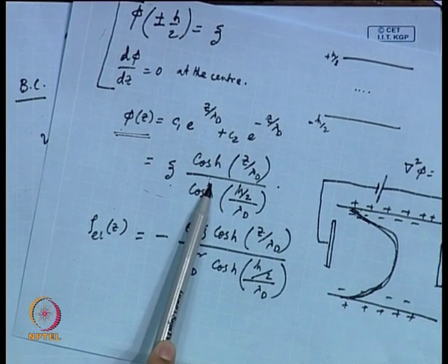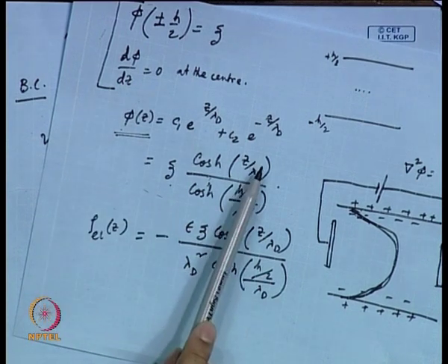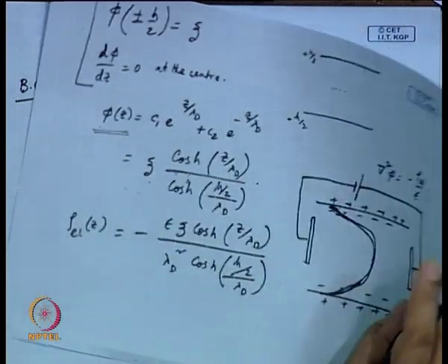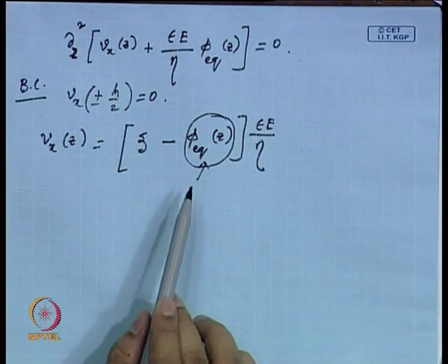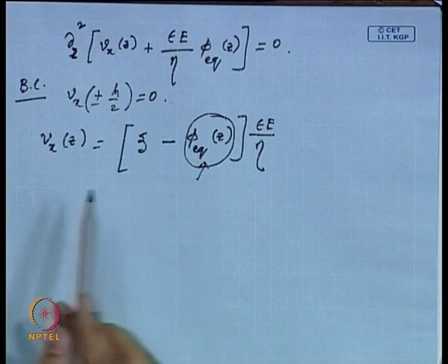All right. So, this phi we intentionally developed for a channel with two walls, to be used as part of this expression, because our final aim, as I said at the very outset, is first to obtain a velocity profile, and second to find out how much flow. We have basically two issues when it comes to electroosmotic pumping. One is how much average velocity you can generate. Suppose I put this pump in place, how much velocity can it generate when there is absolutely no pressure gradient, but simply by electroosmotic flow you are generating so much velocity.